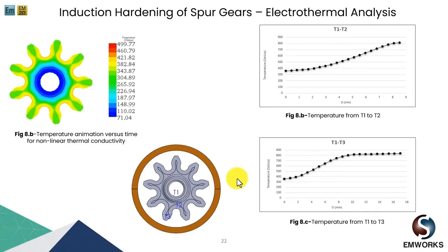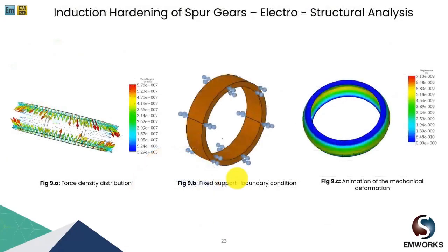Now, what about the generated electromagnetic and thermal stresses? High current may result in higher temperature stresses and Lorentz force in both gear and inductor parts, which lead to structural deformation. EMS can be used to analyze this behavior. In addition to temperature, EMS computes the Lorentz force in conductors with current, so both the thermal response and the electromagnetic response, including the Lorentz force and magnetic forces.